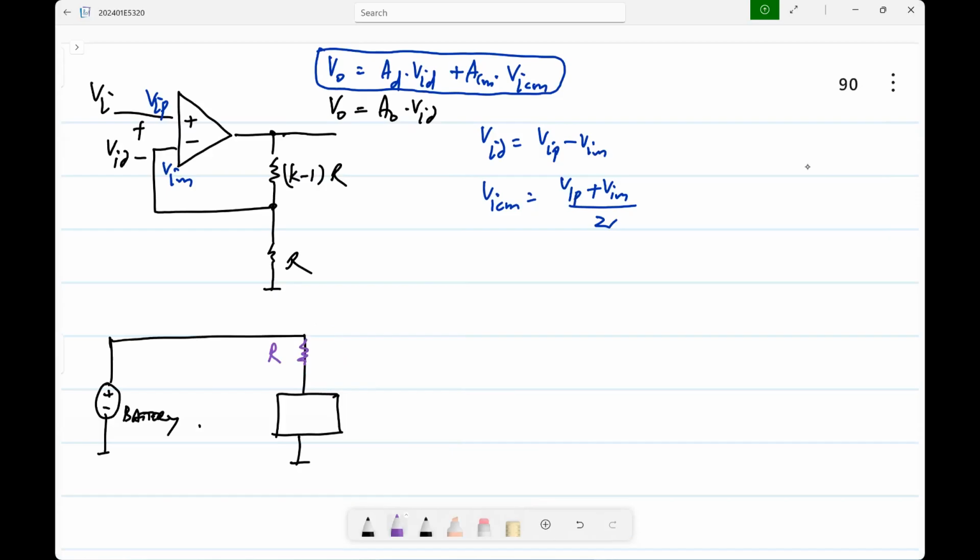In fact, that is how it is measured. You have a small resistor. The resistance should be small so that you don't waste much. And how do you measure the current? You can measure the voltage across that. So now, let's say the battery is some 3.7 volts, and you don't want to waste too much power. So maybe the maximum voltage drop across this could be in the millivolts. Let's say 5 millivolts.